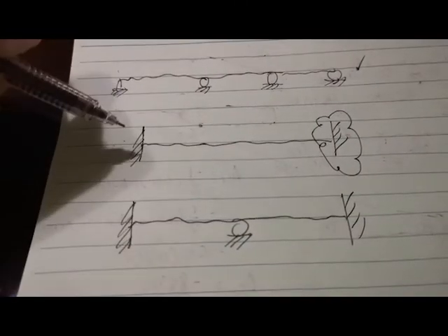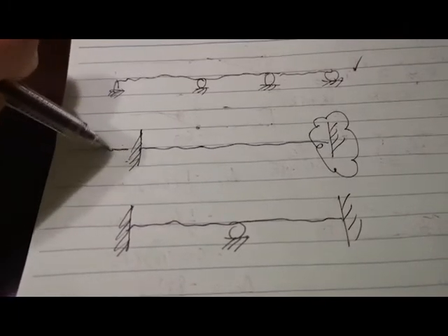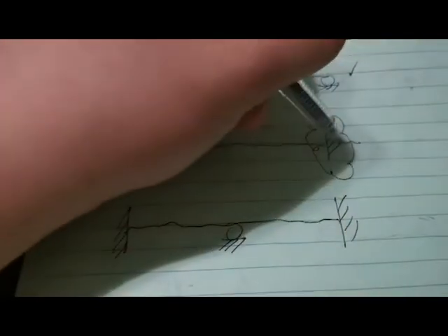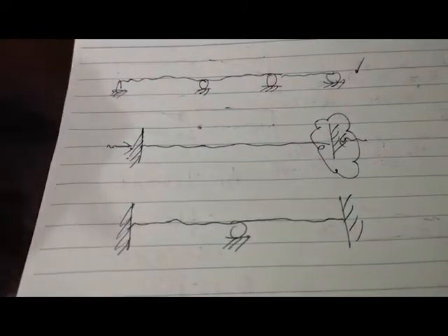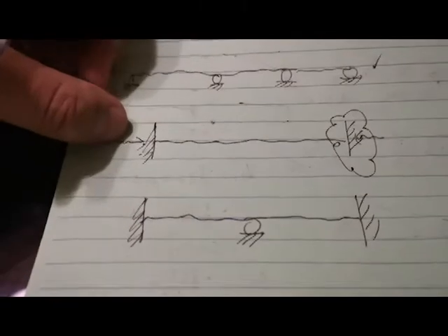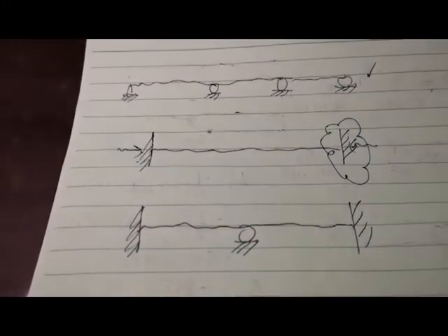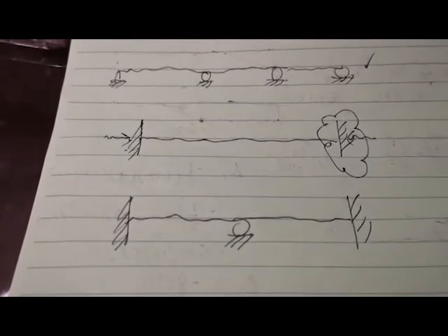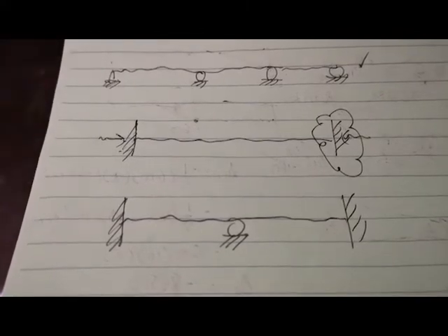Oh, by the way, before I forget, since technically we don't have a horizontal reaction here due to the load being practically vertical, we can neglect the horizontal reaction when computing for the degree of static indeterminacy.